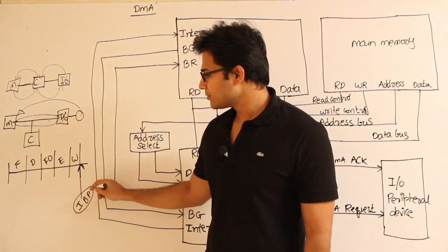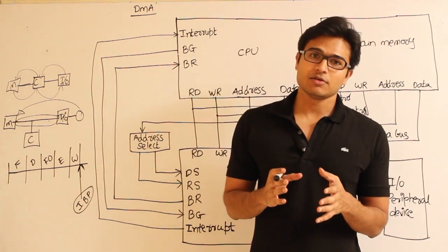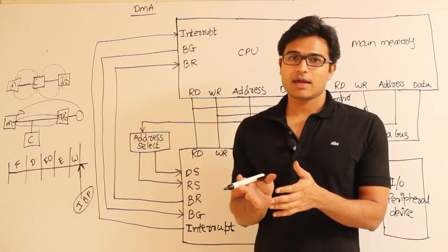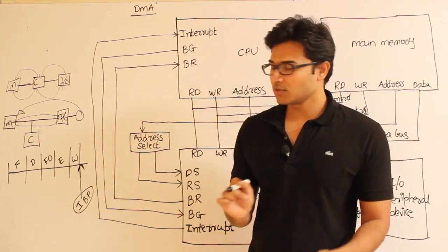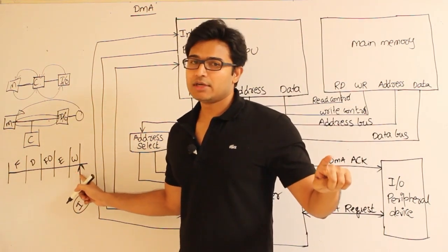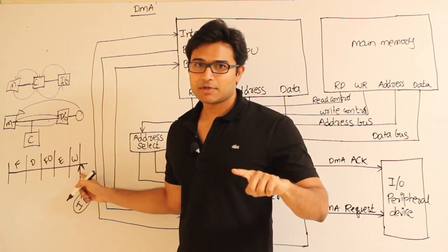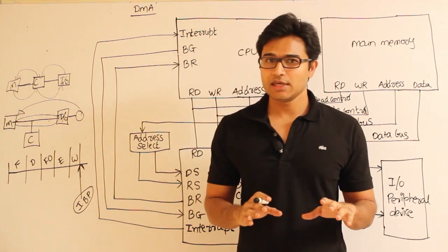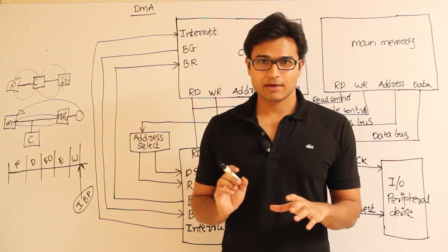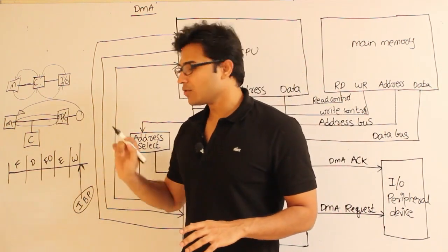Interrupt break point is nothing but when we actually stop the execution of the current instruction and dedicate the attention to the interrupt. So only after executing the complete instruction will we always address the interrupt. We are never going to stop the instruction in the middle and go to the interrupt. Okay, we'll complete it completely and then we go here.